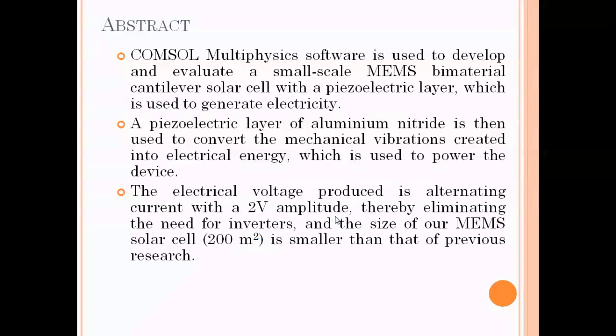The abstract of my work is that we have developed and evaluated a small scale MEMS bimaterial cantilever solar cell which is made up of a piezoelectric layer. The piezoelectric layer is made of aluminum nitride to generate the required amount of electricity. To simulate the results, we used the COMSOL Multiphysics software platform. After simulating the designed structure, we get a maximum electrical voltage output of 2 volt.